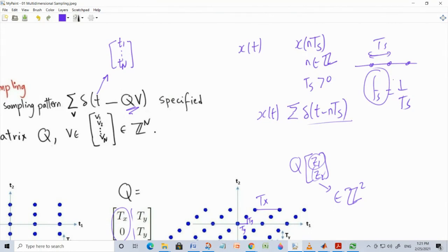So sometimes you take this signal, like when you talk on the phone or something. Basically, your voice is a continuous time signal. It is picked up by a microphone. It is basically sampled using an analog to digital converter, and then it is transmitted. So if the number of samples per unit time increases, then again you are putting more burden on the communication system, on storage, if you basically take these samples and then store them, and so on.